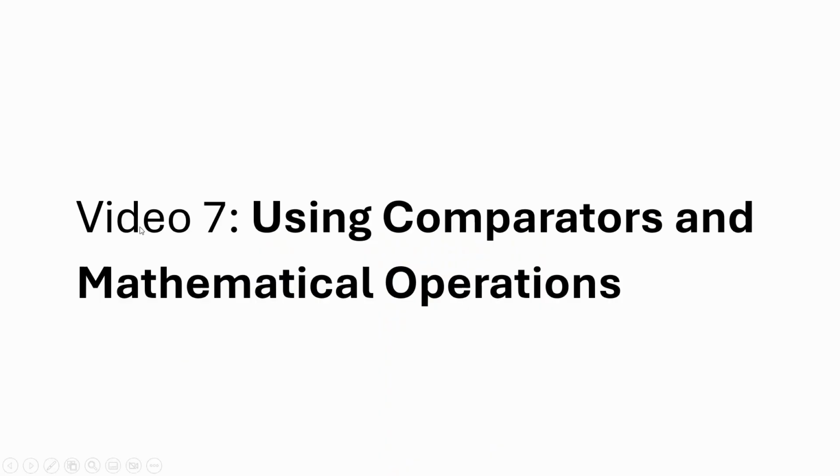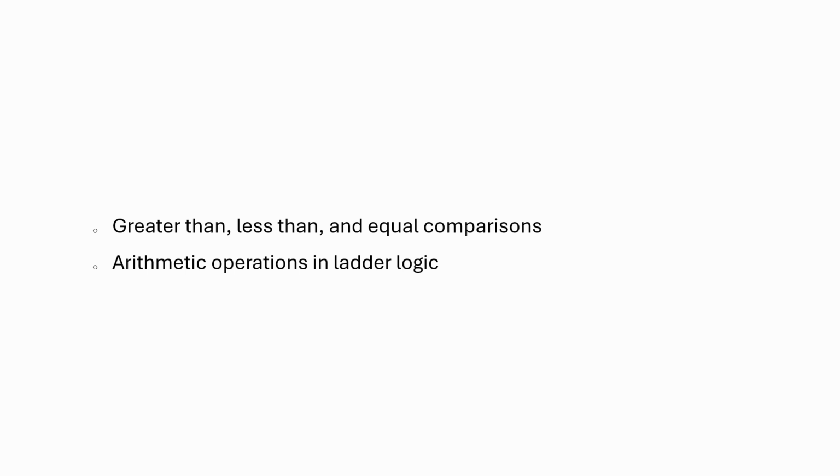Okay, next we're going to talk about comparators and mathematical operations and how that works with the MicroLogix series PLC. We're going to talk about things like the greater than instruction, the less than instruction, and then the different equal comparisons. And then also we'll talk about arithmetic operations within ladder logic.